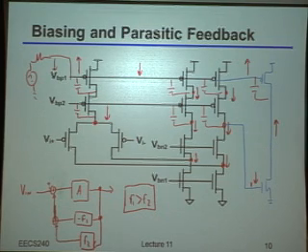Now again, let me ask you guys, what would be a simple way to fix this problem? Let's say indeed you ended up with positive feedback with that particular connection. How do you fix it? Let's see if somebody other than Paul. You could just put a filter on the bias line to reject any... Okay, so you said put a filter on the bias line. What kind of filter do you want to put? Low pass. Okay, so just tell me exactly how you want to do it.